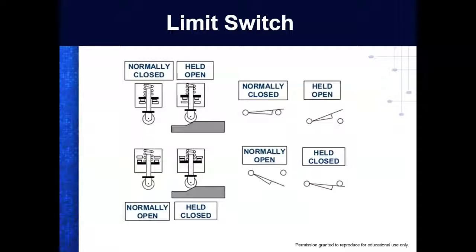That's the symbol for a limit switch. Of course, the device is going to be parked somewhere. The problem is that some of the limit switches might already be made, or they might already be open. So at the top we have normally closed and normally open. Can you see the way they're drawn? It's got the little plateau, the little ramp up here.